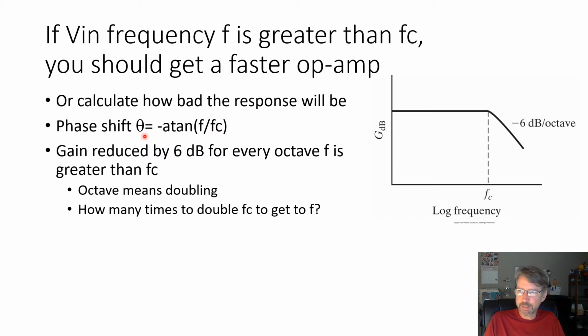The other thing is, you can see as frequencies increase, the gain decreases. And so we approximate this with a straight line when we have log scales, and this is a log scale since it's in decibels. A straight line, and the slope of this line that starts at the baseline gain and corner frequency goes down at -6 decibels per octave. And so the easiest thing is, if you had this graph, you could just see, well, I'm operating at this frequency, and pick the gain off of there. So most of what we're going to do is just how to calculate this change on this graph.